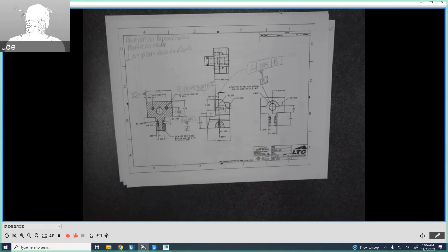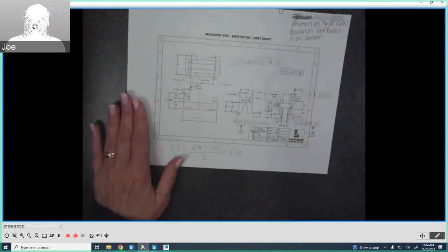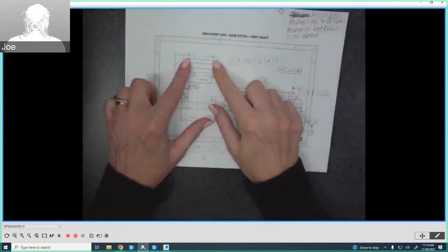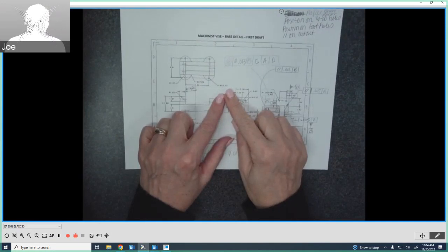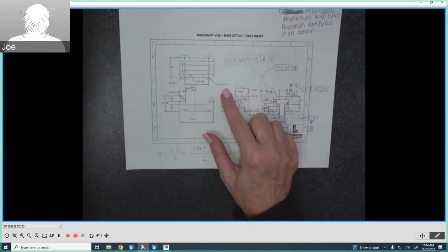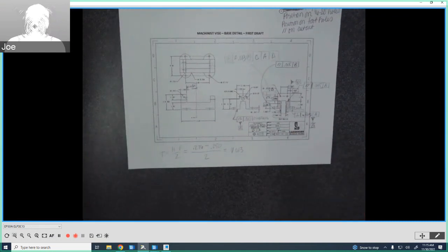I know we only added a little bit of the GD&T, but I was just looking at the mounting holes on the base. Do you think those would normally need it? Well, I will say this, on the mounting base, these holes are going to be quite generous based on the fastener size. For instance, I would anticipate that a 1/4-20 socket cap screw would go through there. So we are looking at about 1/8 of an inch clearance. So it's already quite generous with the size of the hole.